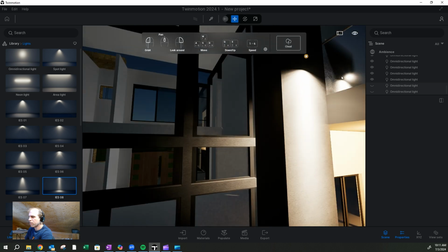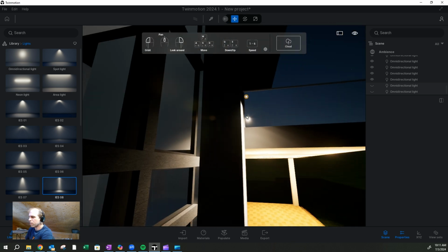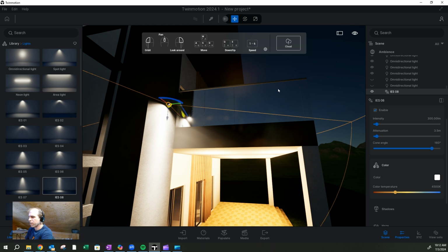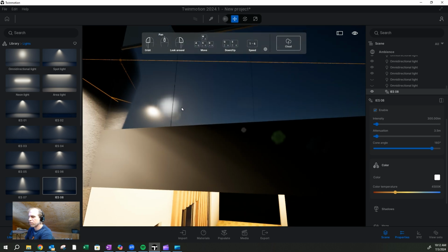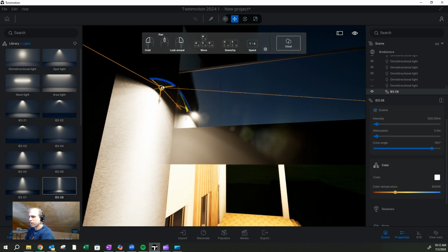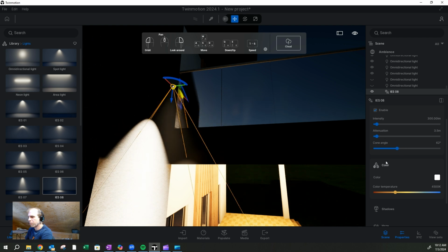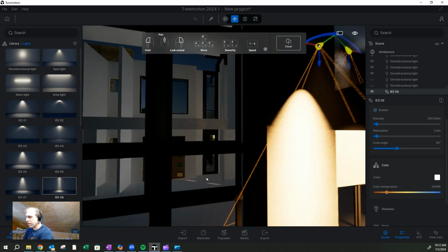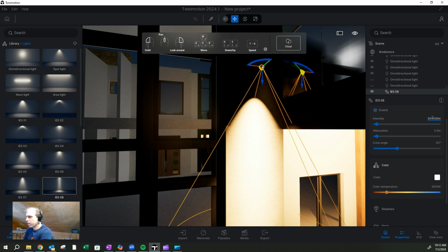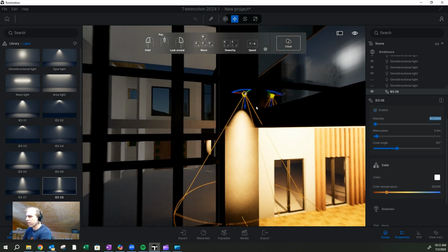We'll come in, and this is where the lighting design comes in, and you get a little bit more specific on fixture placement, beam angle, those types of things. Color temperature, we'll adjust it to 3000K. Maybe have it on a schedule on a dimmer, so that it's programmed to only come on, maybe even just 50 lumens, nice and soft there.